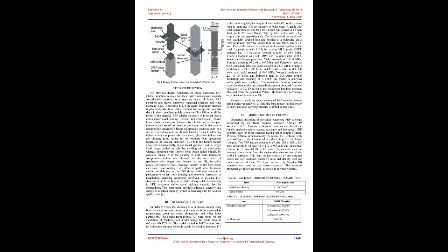4.3 Numerical analysis. In order to verify the accuracy of a numerical model using finite element software, numerical analysis from a journal is reproduced using its model dimensions and other input parameters. The details from Journal 2 were opted for the validation of the numerical model using the finite element software ANSYS 16.1. The model named B170-8 was taken for validation purposes, where B stands for bending loading, 170 is the bond length/splice length of the steel FRP bonded sleeve joint in mm, and 8 is the number of bolts used.